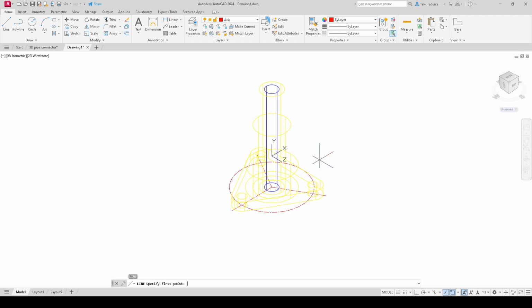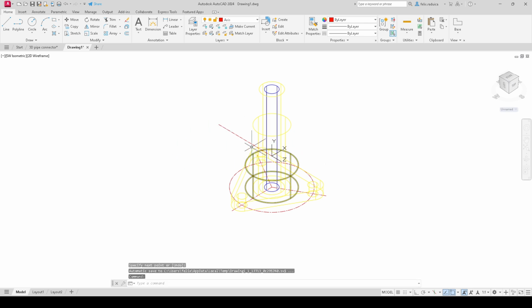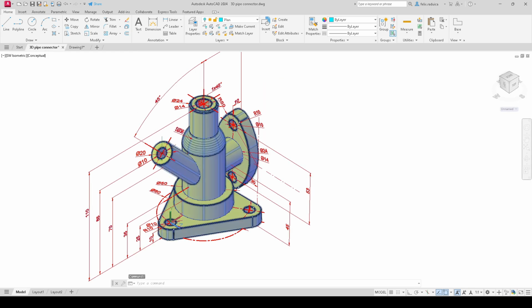and we'll give the line command 0, 0, and now we'll use relative coordinates, polar actually, at, and then I'll give 100 millimeters, less than, and now this is 135. Tap enter twice, and this is our axis line created for the two tilted cylinders here.